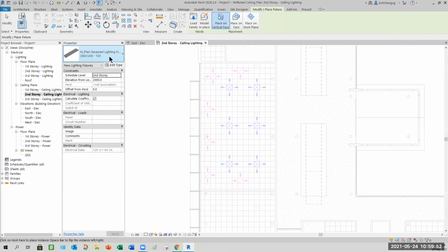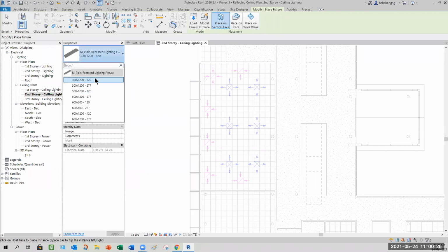So in other words, if you later place lighting fixtures in the open ceiling, like your first story, it will be very challenging. So we'll do it together and see what library we can have. When you're doing this, you must turn on your 3D view. Don't just do it in the plan, and the same goes for the elevation. So be careful. Now because we have a ceiling, you'll notice that this particular lighting fixture is not suitable for this style of ceiling.